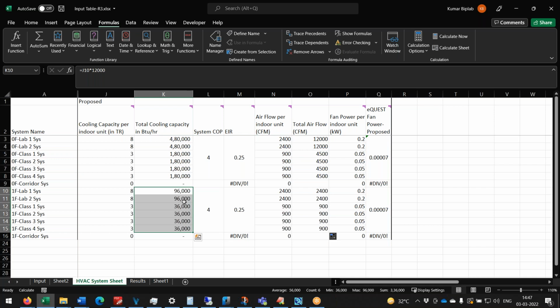Okay, sir. Here, what is the sum we got? This 96,000, and we got around 3 lakh, right? 3,36,000. So this 36 is 28 ton. Then the condenser TR, how much should it be? Maybe around 25 should be okay. 25 ton. That's where the compressor work is not accounted.